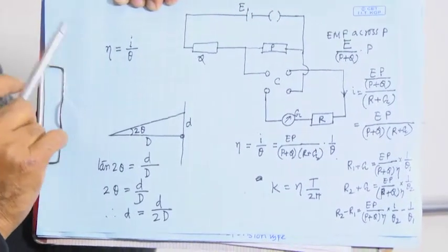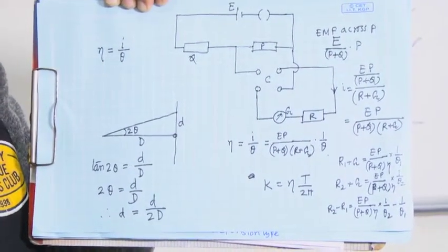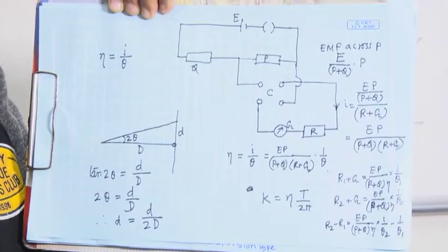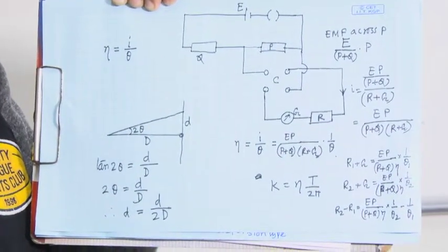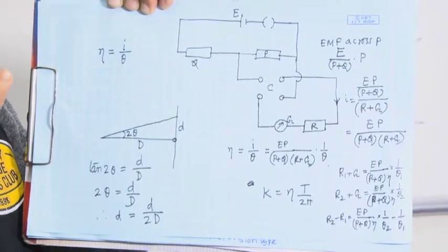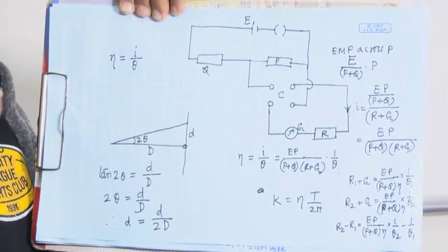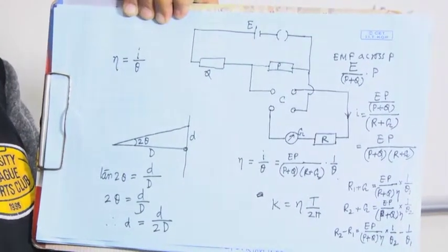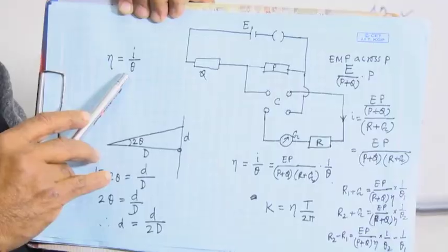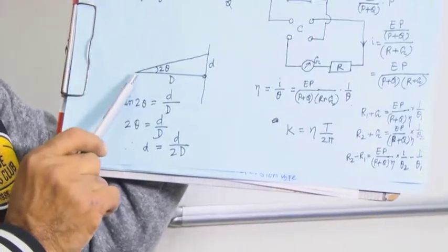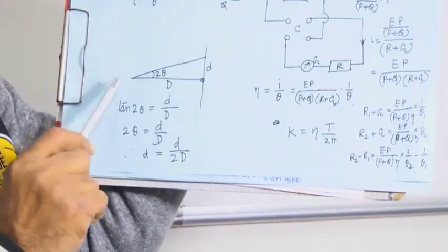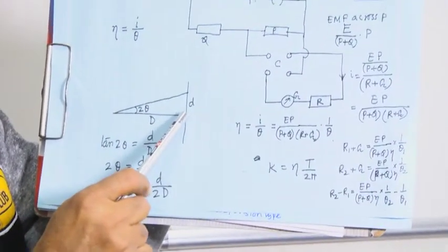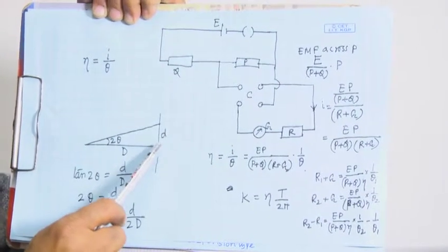So, now I have to pass current through the coil of the galvanometer. Then I have to measure the deflection of this coil. So, I need an arrangement for passing current through the galvanometer, and then using the light scale arrangement we will measure theta. So, when the mirror is rotated by theta, this reflected light, this is the initial light at 0 position.